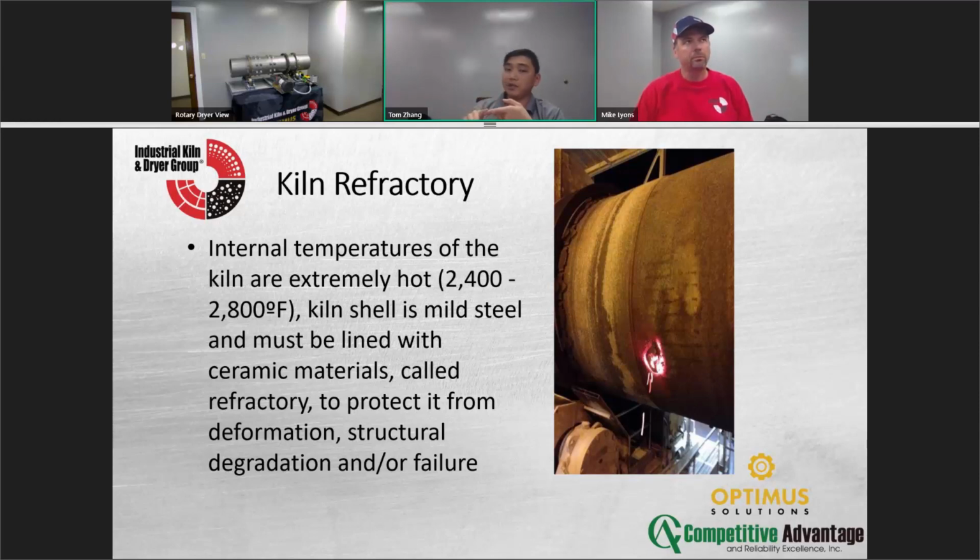If you have any misalignment in your burner, where the burner nozzle is into the refractory and, in a sense, melts it, you'll have something that you will see on the right. Typically, that'll be in the discharge end, really hot, where the burner is not aimed right. So this is where an audit's good. Have your burner guy tune it to make sure the angle is right on the kiln. We provide that service too. You don't want a hot spot. Typically, that's a shutdown situation. Right. Very dangerous.